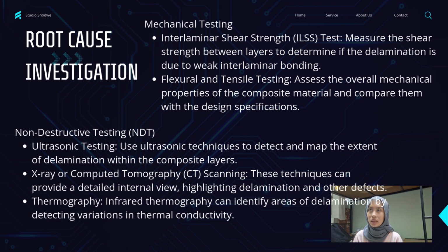Second is mechanical testing. For mechanical testing, we use ILSS, which stands for interlaminar shear strength, and flexural and tensile testing.